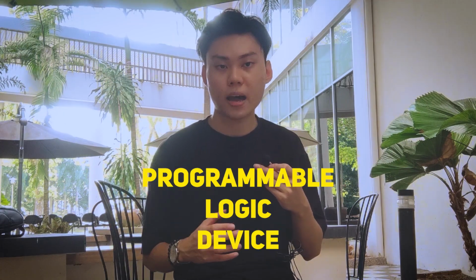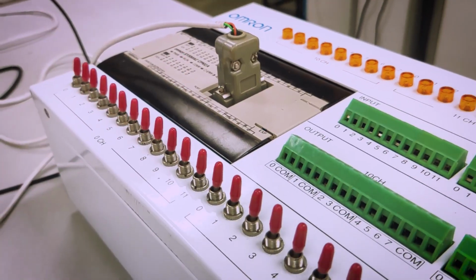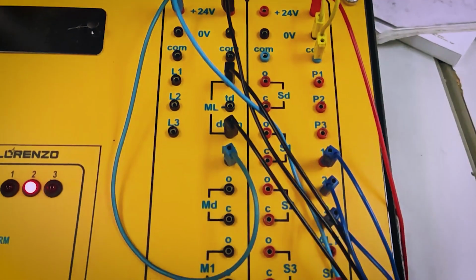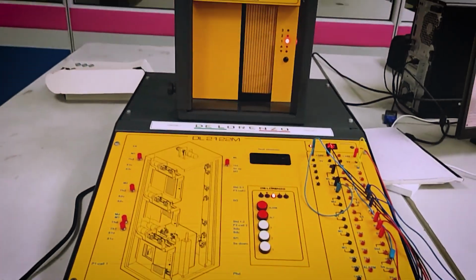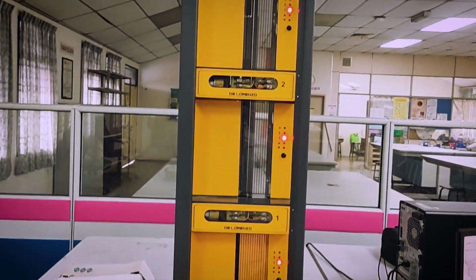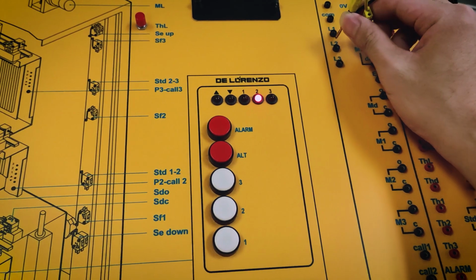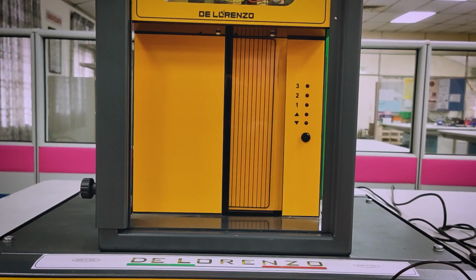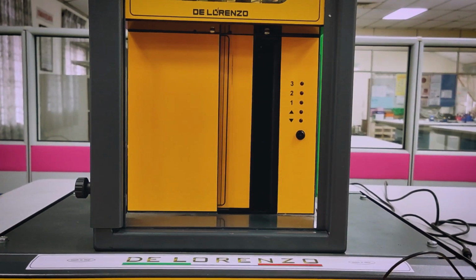In modern elevators, the device that is used to control elevators logic is called a Programmable Logic Controller (PLC). The PLC is connected to various sensors and devices in the elevator such as the door selecting buttons, door sensors, as well as the motor controller. It receives input from these devices and uses that information to control the elevator movement, including the opening and closing of doors and stopping at the desired level.